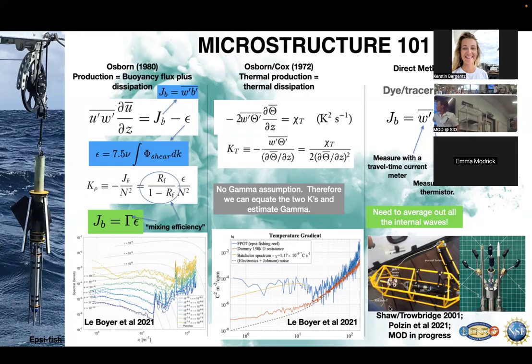I get this thing, which is called shear production. This is saying how much energy the turbulence is getting from the shear, so that's the energy going into the turbulence bank account. And then the buoyancy flux: if it's a stratified fluid and there's mixing being caused, the buoyancy flux is always going to be taking energy out of the turbulence, right?